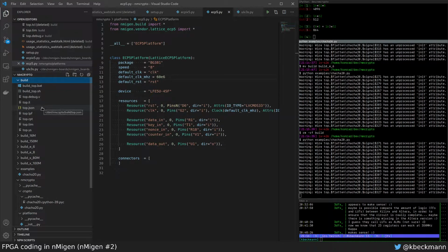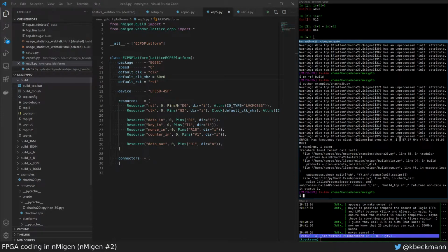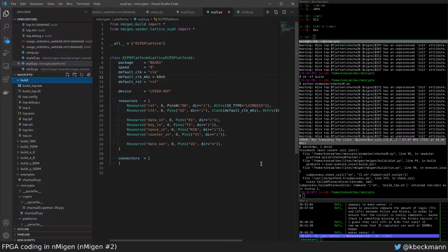Maybe we should do the Xilinx approach. Target a high clock and then see how much we went over. Yeah, because now we got a fail at 56, 57. Oh, right, wait a minute here. If I remember correctly, the 5G parts are not just running at speed grade 8, but they are also running at 1.2 volt instead of 1.1 volt, and that gives you quite a significant speed boost as well.